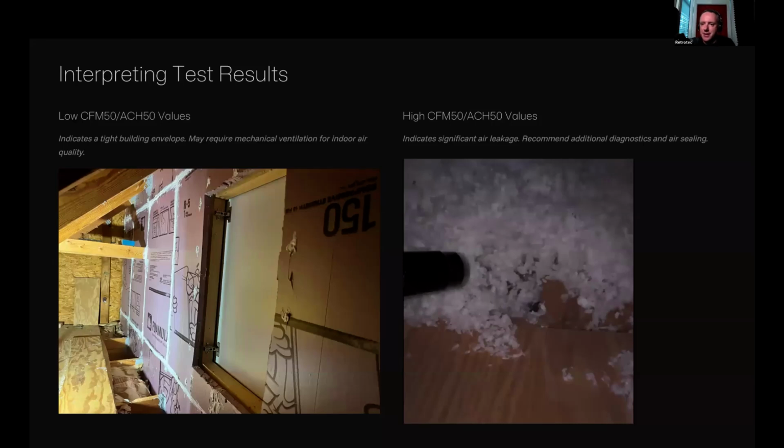It's completely different than anything else you've ever seen if you've never seen one. But I would think it would work for most instances if it's installed in the right direction. That could be a common issue with that. Maybe they just flipped it around the wrong way. But once it does close, it does get a nice airtight seal. There's nowhere for air to go. But yeah, the dampers that come on those builder grade bath fans are pretty crappy.